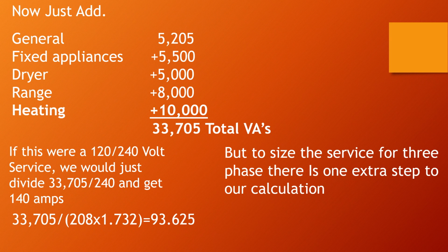Obviously, you'd size your wire according to the amperage load, make sure it covers it at a minimum, and then you're going to select a standard ampere breaker rating from 240.6(A).